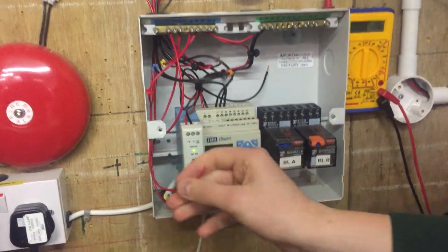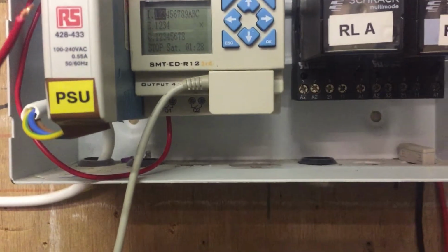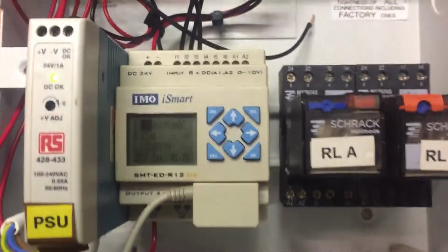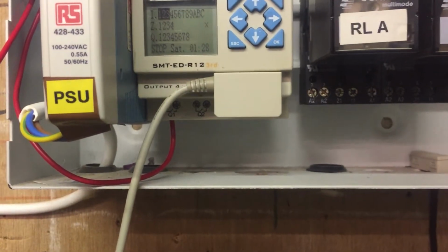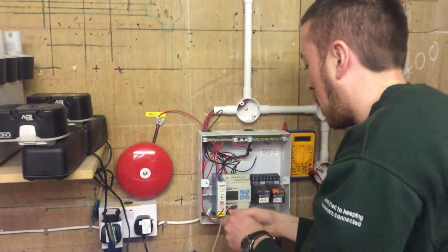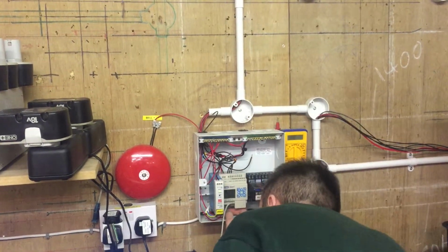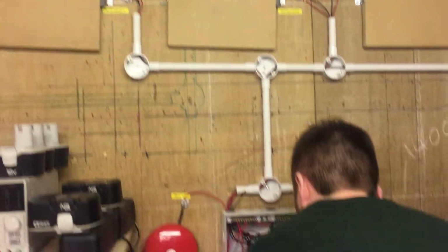Once all the inputs are connected, you'll need to connect up the output, the bell in this case. We've already connected positive to the bottom of the PLC in the Q1 output. We'll now connect the bell to the other side of the switch to complete the circuit. This means that when the PLC is activated using the software, the alarm will sound when one of the doors is opened.